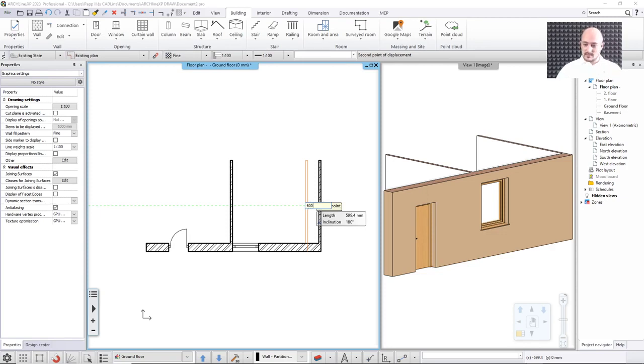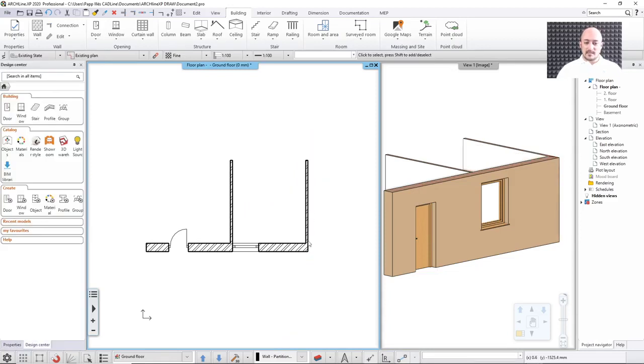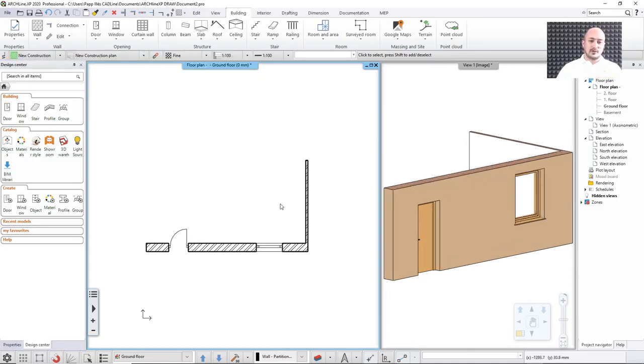Okay, let's say just like that, I'm working in millimeters. So now what happens, because it's automatically connected, the connection of course changes, but see what happens if I just moved it. The software changed the future as well, because those things that you do not mark to demolish, when you move them, will be treated as continuously existing items all through to the end of this project life cycle.